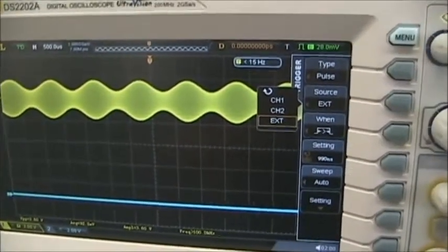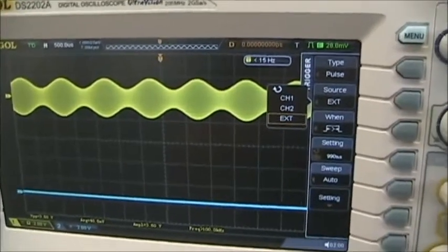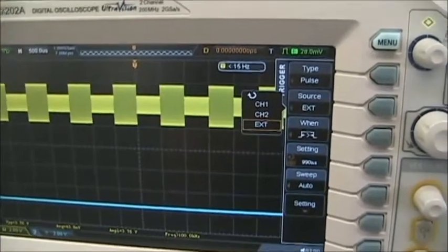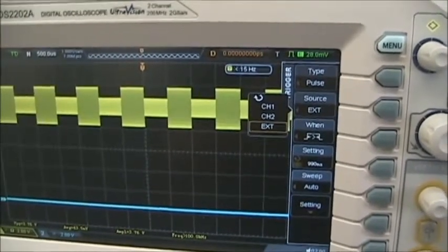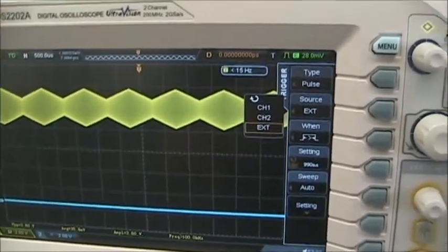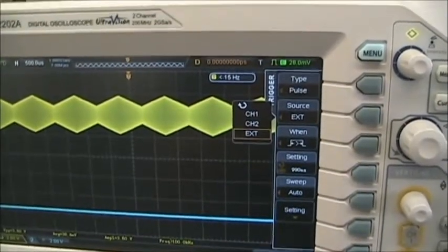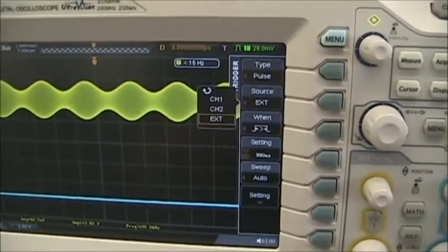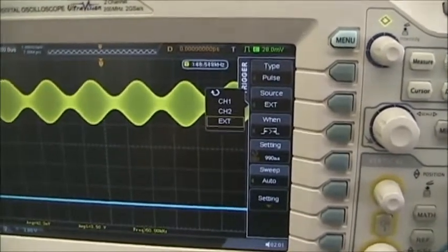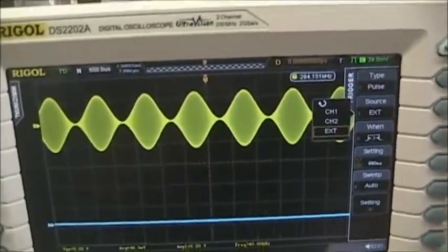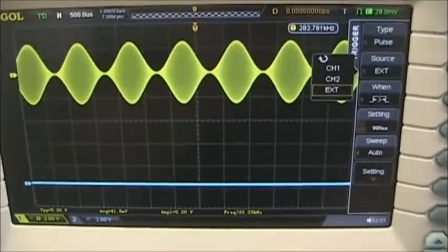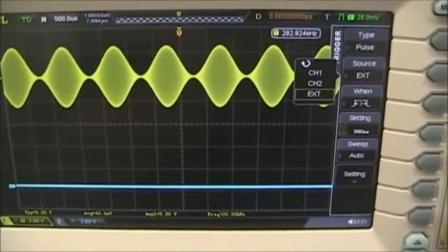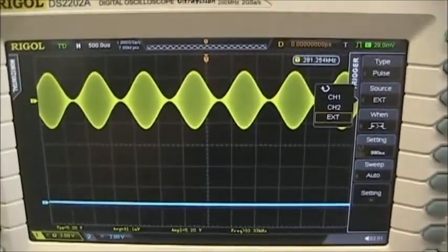voltage. I can also change the shape of the signal. I can change it from sine to square to triangle. All of those are selections that I have available to me. I'll return it to the shape of a sine wave and the modulation index of 100%, since that's a known type signal. Now we are ready to look at the demodulation of this AM signal.